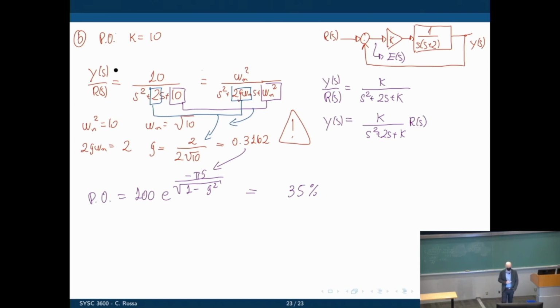Okay, so that controller gain is too high, and the system is too aggressive. It results in overshoot. Hence the next question: if this doesn't work, then what is the maximum value of K that results in no overshoot? In that way, the robot goes just in front of the eye, touches the surface of the eye, but doesn't puncture the surface of the eye. How do we do that?